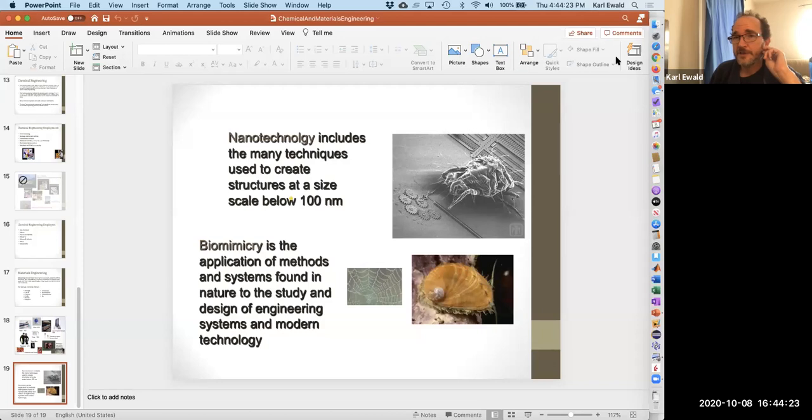In silk screening, you take an image and use a photo process to put that image on a screen, and you have resist. When you squeegee the ink through, it goes through the empty spots and not through the filled spots.